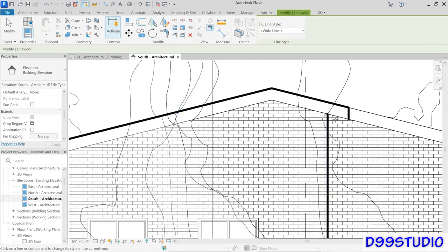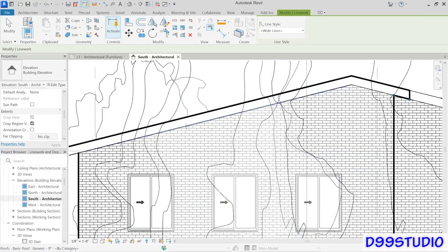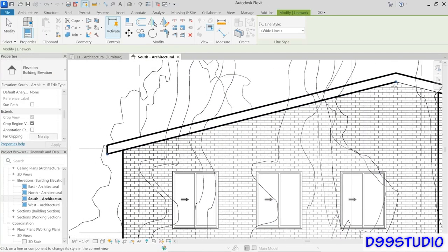Now, if you click under the eaves, it's going to go all the way across, and I don't really like the way that looks. But notice the little grip here. You can simply stretch that back to that location and adjust the effect so that it only applies to part of that line. And I think that is a really nice benefit of this tool.